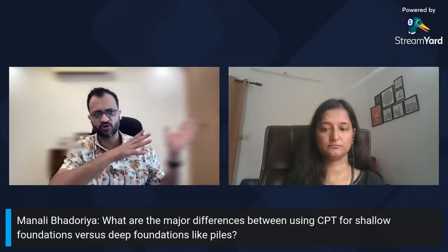Because the test is actually mimicking the foundation installation, CPT data historically has been very popular for determination of pile capacities in situ, and especially offshore where you don't have time to do boreholes and lab testing. People have been using CPTs for years for a quick determination of fairly accurate pile capacities for the offshore industry. But it's equally applicable to both.